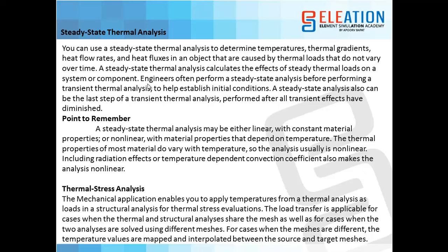So the mechanical application enables you to apply temperature from a thermal analysis as a load. Here we apply temperature as loads instead of forces or pressure or moment, and calculate structural analysis for thermal stress evaluation. The load transfer is applicable for cases when the thermal and structural analyses share the mesh, as well as for cases when the two analyses are solved using different meshes. So we can have the same mesh or same model to perform the thermal stress analysis and steady state thermal analysis, or we can have different meshes.